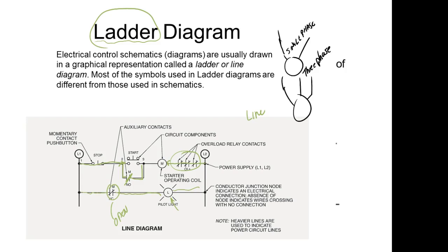When it's starting. We call it start current. It's also stall current. They also call it locked rotor current, which means if you were to lock the rotor on the motor and put power on it, it would pull start current. But if I leave that start current on the motor, the motor's going to burn up because it's not designed to handle that start current for a long amount of time, right?